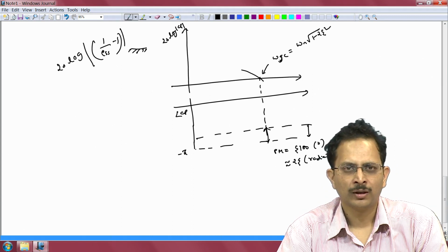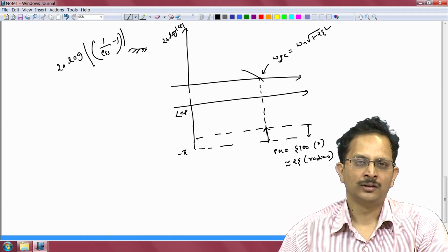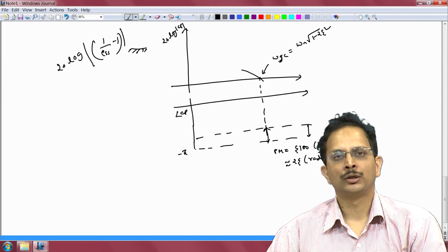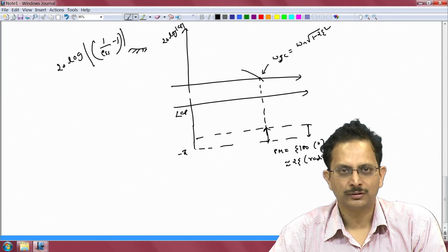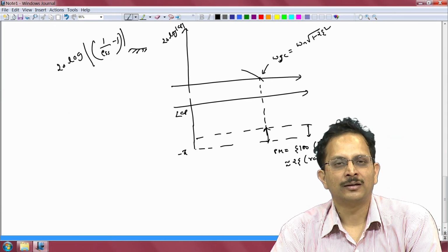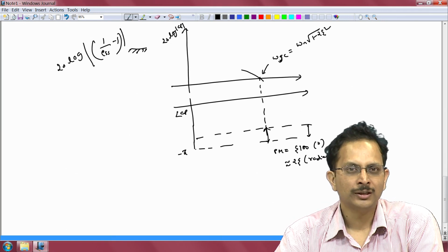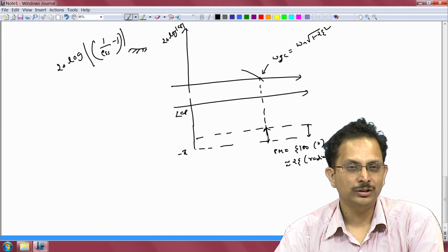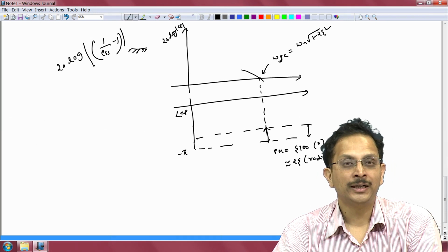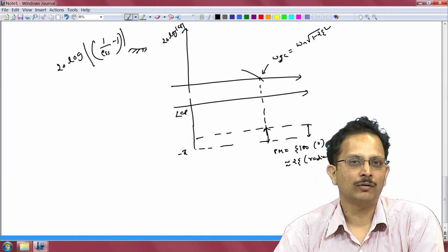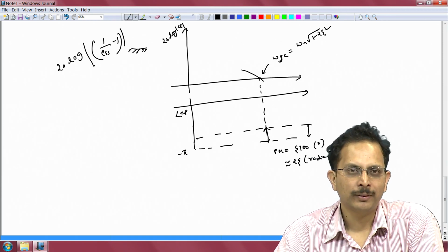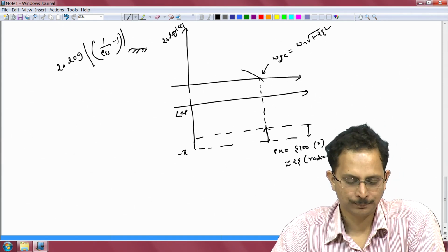and if you notice here, we have made approximations all along from time domain to closed loop frequency domain and from closed loop frequency domain to open loop frequency domain conversions. Therefore, when we do the design using Bode plots, it is imperative for us to convert the designed open loop transfer function into the corresponding closed loop transfer function to see if our closed loop frequency domain specs have been met correctly, and subsequently to plot the step response of our closed loop system and see whether the time domain specifications have been met by the designed closed loop transfer function.